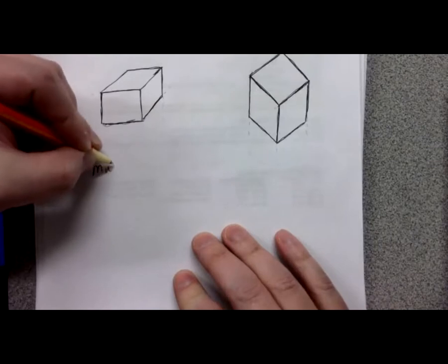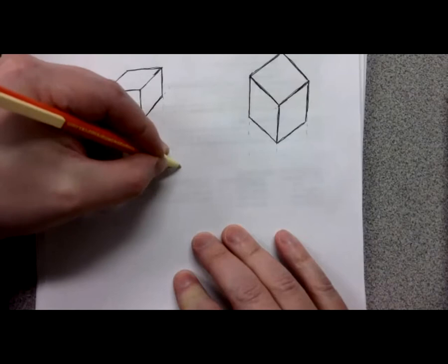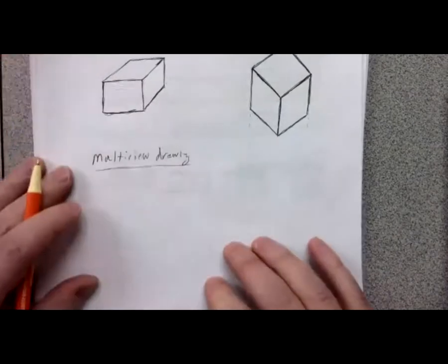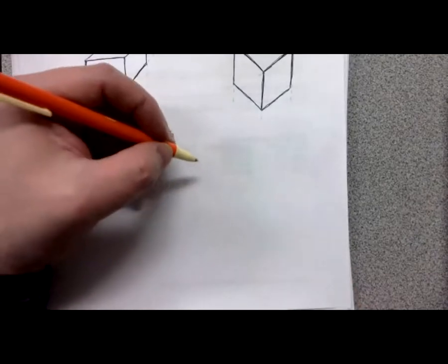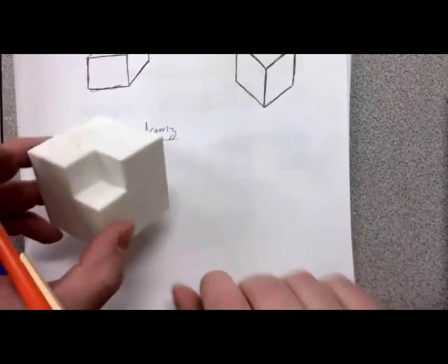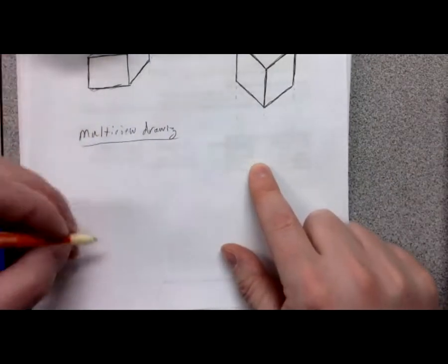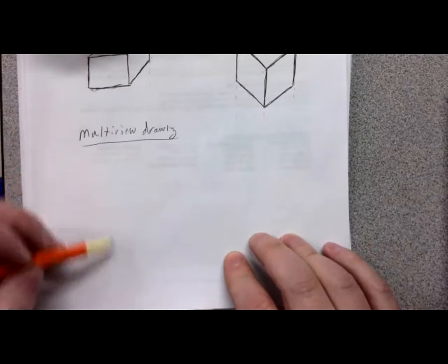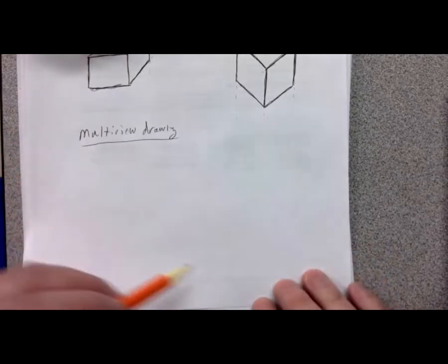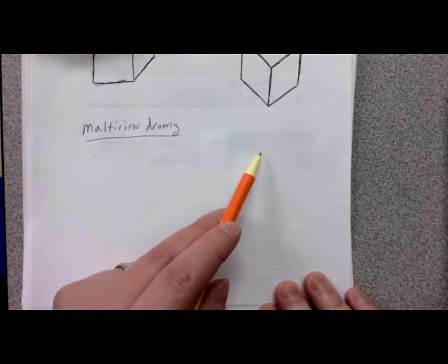So if we look at a multi-view drawing again, and if we draw this thing, I'm going to draw it kind of roughly with you here. I'm going to draw the pictorial. But a common thing that we do with the multi-view drawing is we draw the top over here, we draw the front here, and we draw the right here. And then we'll put a pictorial up here in the corner. Okay, that's the common way we're going to do this.